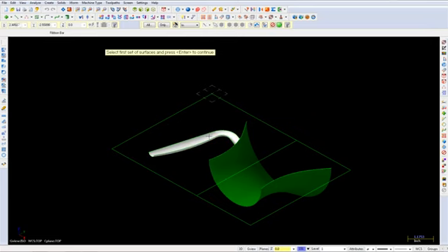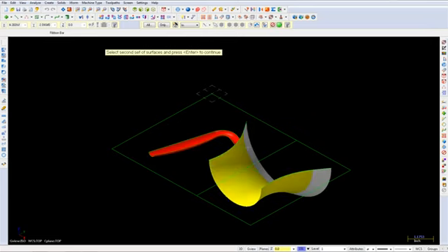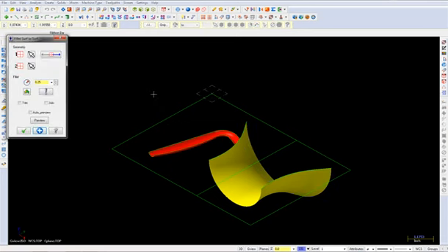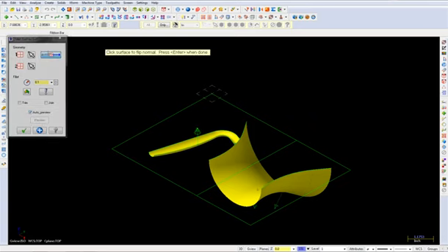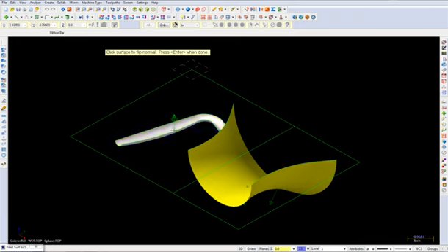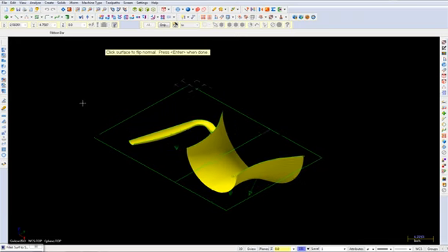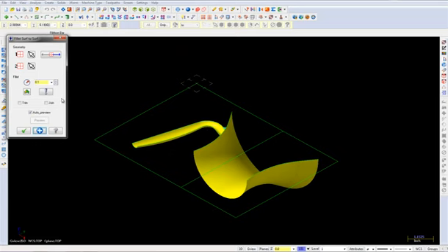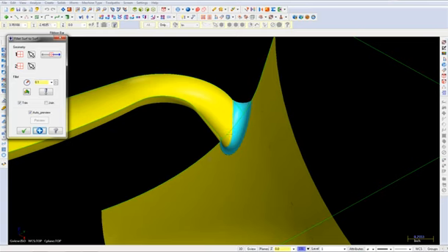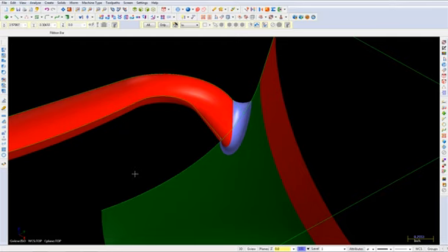Choose this surface here and press Enter. Then select these two surfaces and press Enter again. Change the fillet radius to 0.1 inches and enable Auto Preview. Click on this button to flip the surface normals. Ensure that all of the surface normals are pointing downwards and then press Enter. Select Trim once complete and your fillet should appear as shown. Select the OK button to exit the command.